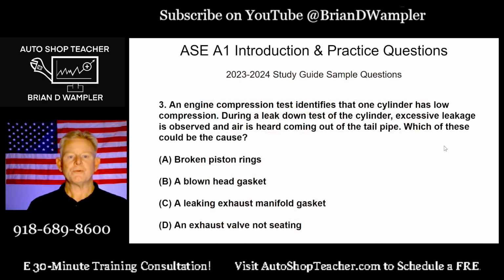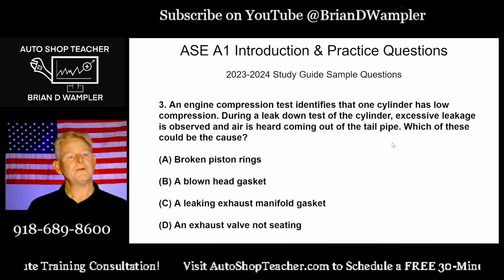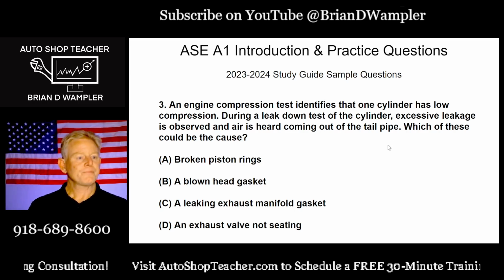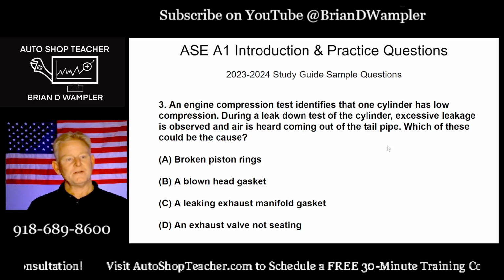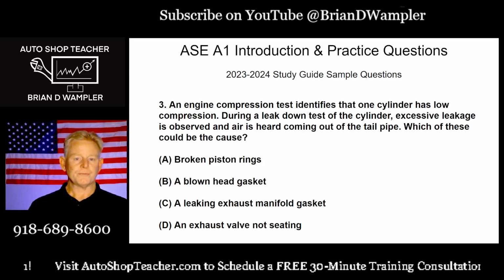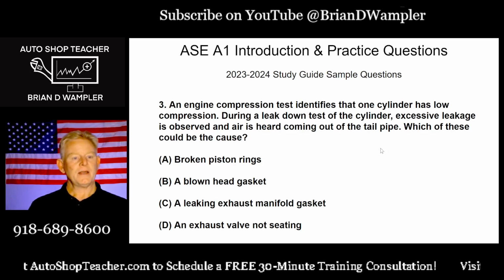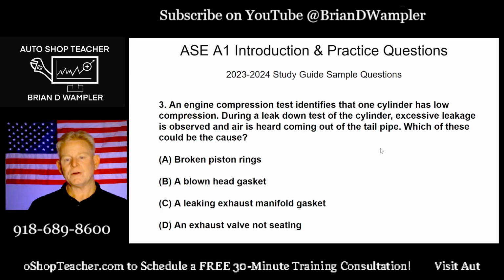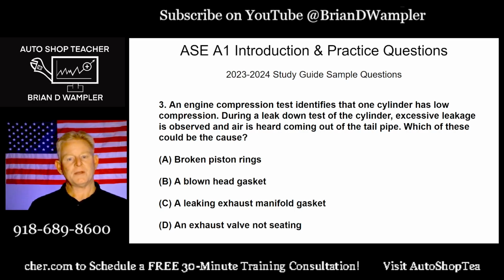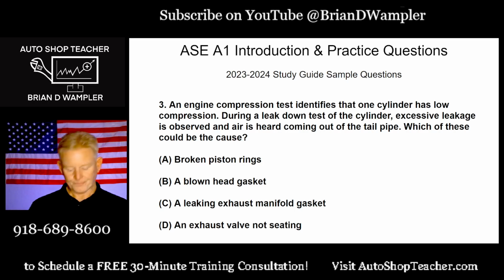All right, question 3, again, another multiple choice one. So far we just have standard multiple choice questions in these examples out of the study guide. This one says, an engine compression test identifies that one cylinder has low compression. So one cylinder, low compression test. During a leak down test of the cylinder, excessive leakage is observed and air is heard coming out of the tailpipe. Which of these could be the cause?